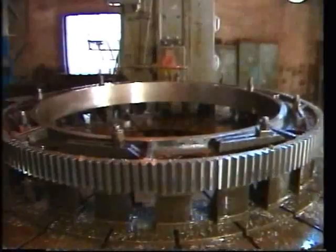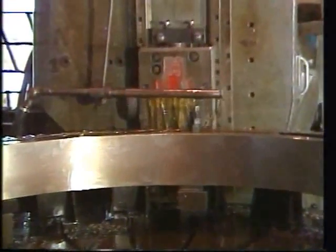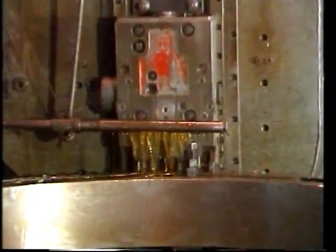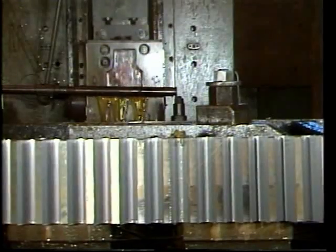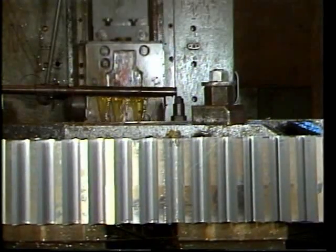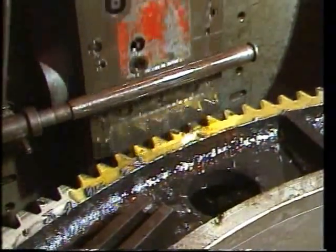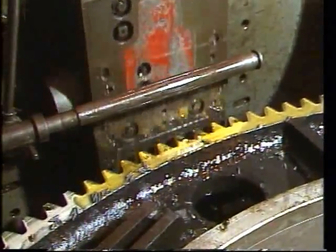In case of large gears, an initial rough cut is made before taking them for gear generation in order to quicken the process. Gear shaping using rack cutter is one of the gear generation methods. The rack cutter reciprocates through the face width of the gear blank. The gear blank also moves relatively. The relative motion of the gear blank and the rack cutter is in such a way that they mesh and roll together as rack and pinion.